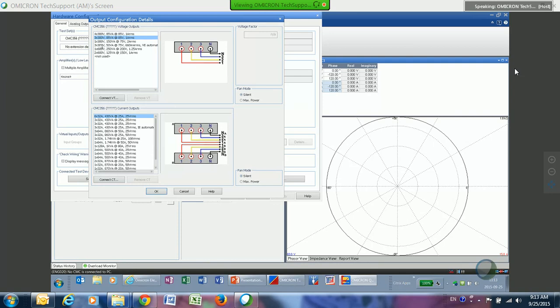If I don't need that 4th voltage, I can come down and select 3 by 300, and that basically will only give me the 3 voltage outputs. We only have one bank there, so this would be channel A on our voltages if you want to look at it that way. If I only want a 300 volts, I could use 4, or that 4th output.